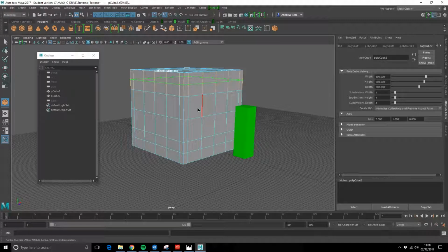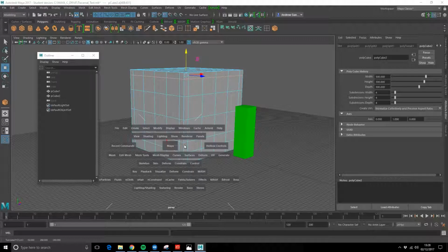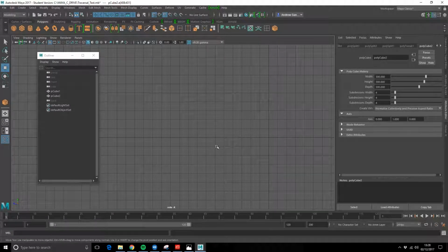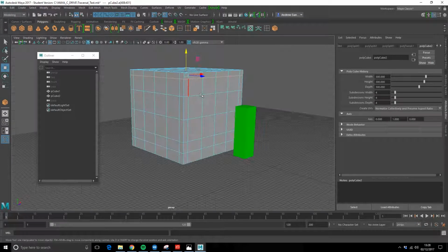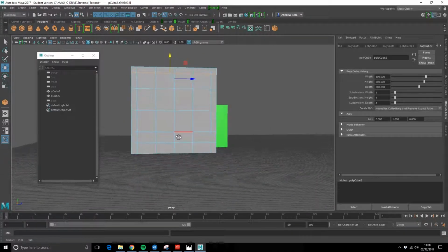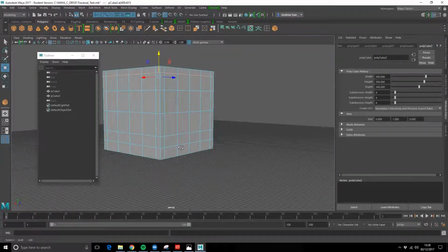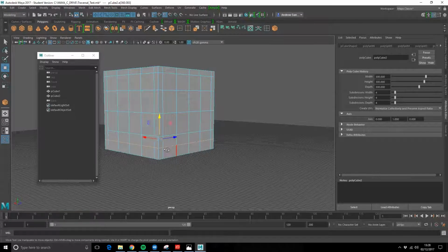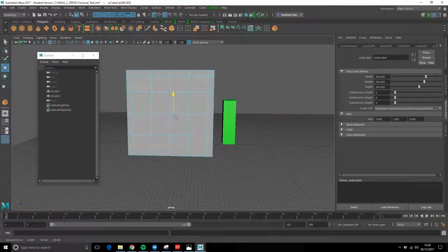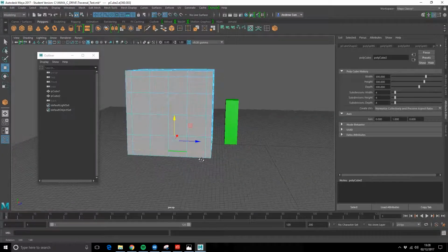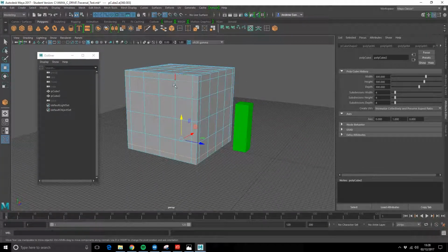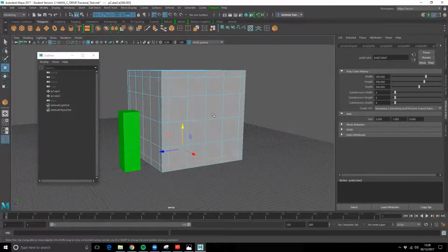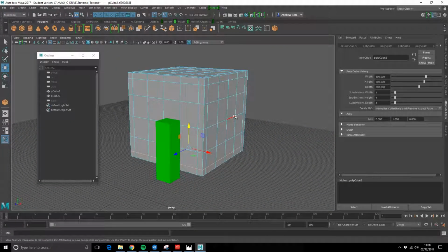So that's fine. So now I can grab this edge and I can move it back in again to, whoops, a daisy. I don't want the side view, I want the perspective view. Quite hard getting used to this right clicking menu system, but double clicking on there, I managed to select the whole loop, and then I can drag that down and make it 20 centimeters width. So we've got a roof and walls all 20 centimeters. This is the block shape that I want.